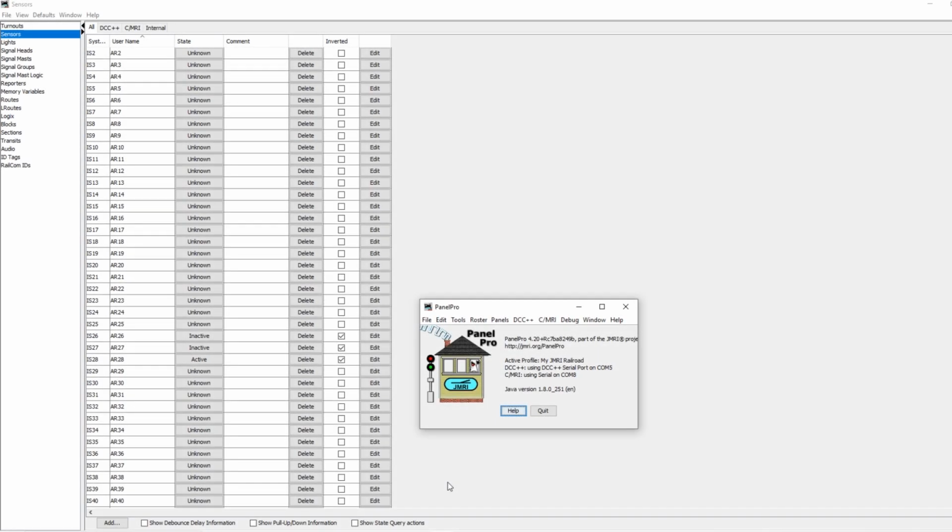So in this first level of automation, we're going to use simple signal logic, SSL, to add some rules to our signals so that JMRI will automatically know if they should be set to danger or not. This will work with analog layouts and digital layouts. This will work for you if you still want to manually control your trains, but it's also necessary for the next 2 levels of automation as well.